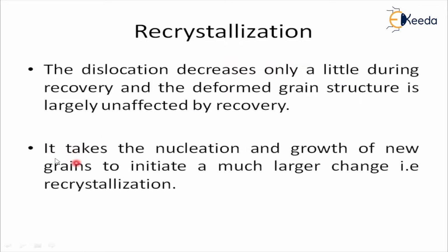The main feature of recrystallization is the nucleation, the starting of the grains, and the growth of new grains to initiate a much larger change. So that is usually represented as recrystallization. This happens in the material. That's why recrystallization is compulsory for any material after the recovery process is completed.